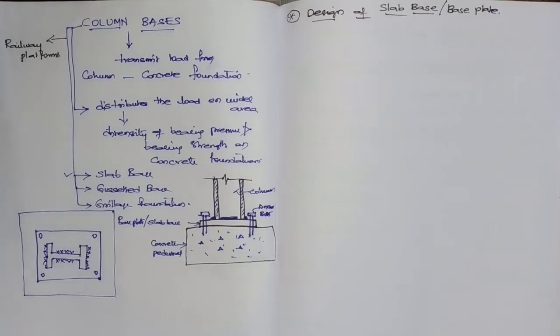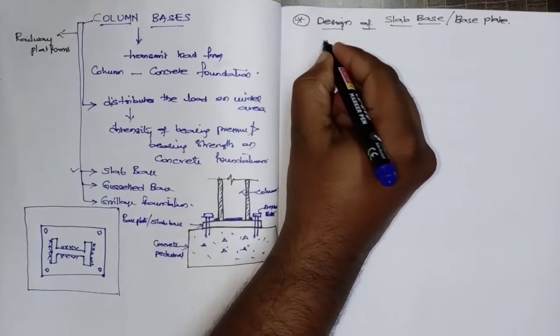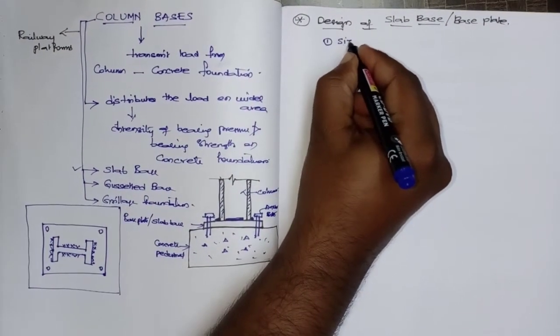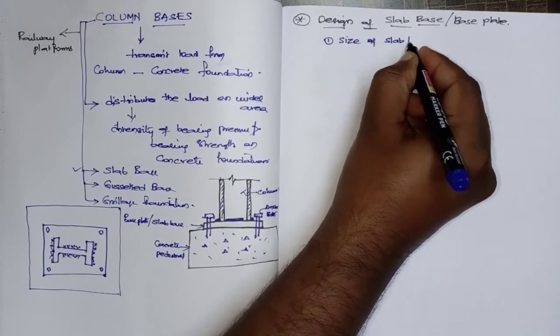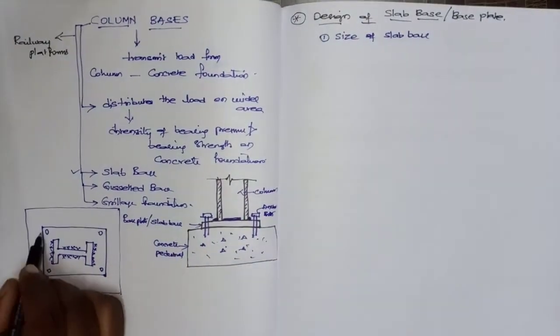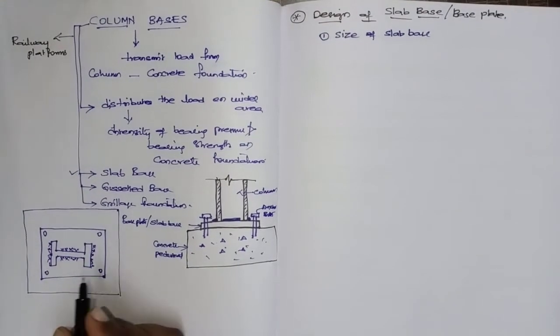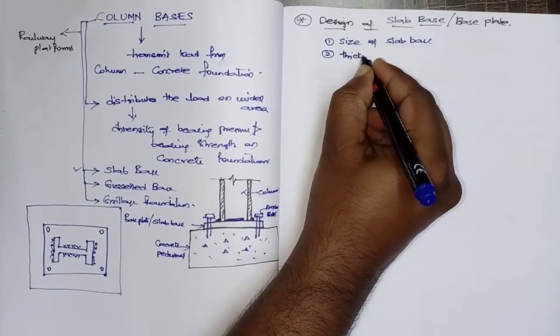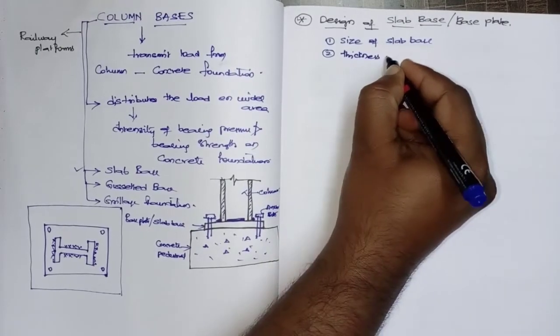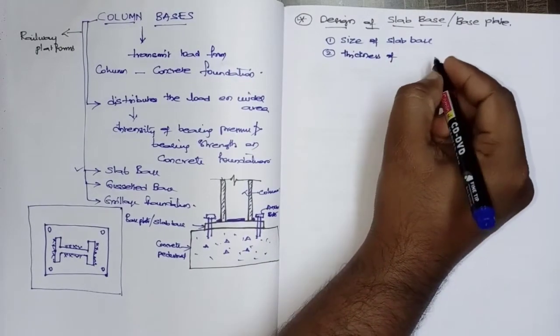Now the steps involved in design of slab base: first you are going to decide the size of slab base, means dimensions, length and width. After that, thickness of slab base.